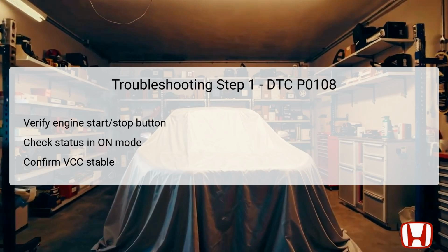It's imperative to determine that the engine produces an adequate voltage supply, known as VCC, which must be stable for the MAP sensor to operate correctly. Conducting a visual inspection can reveal loose connections or damaged wiring that may compromise the sensor's performance. Ensuring these conditions eliminates basic operational failures from the diagnostics process, making subsequent steps more effective in identifying the fault.